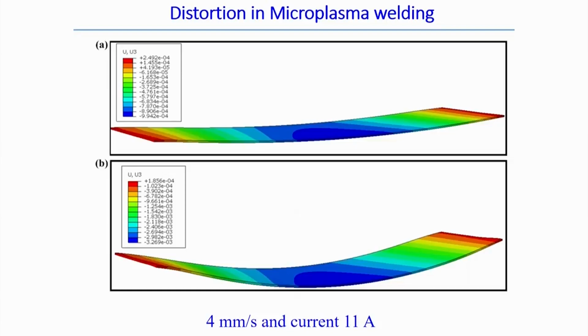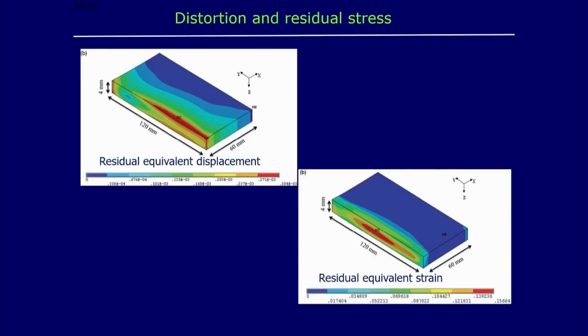In the first case, the small displacement theory was considered, that means when you relate the strain and the displacement, we do not consider the nonlinear component of the displacement. In the second case we consider the local behavior, that means the nonlinear part of the distortion, and that predicts more precisely the distribution of the distortion in the case of a very thin sheet. Therefore, in very thin sheets we should use the large displacement theory to predict the displacement field.